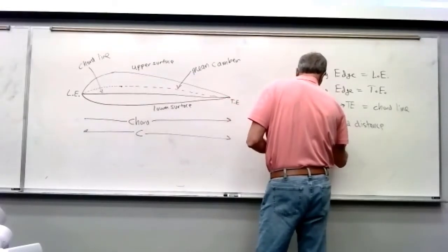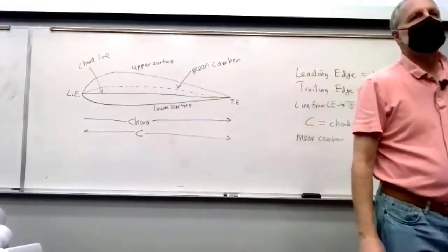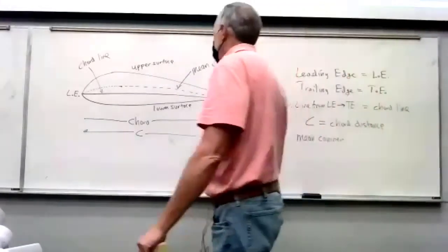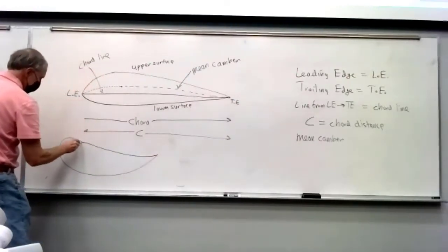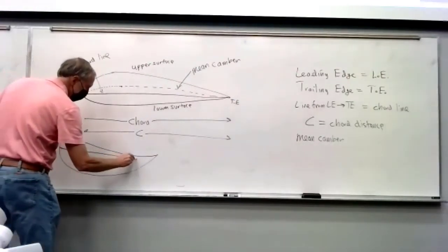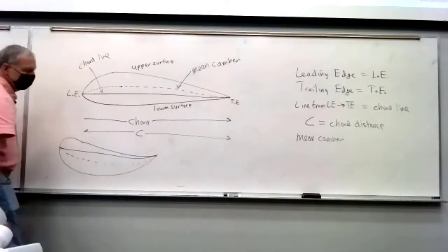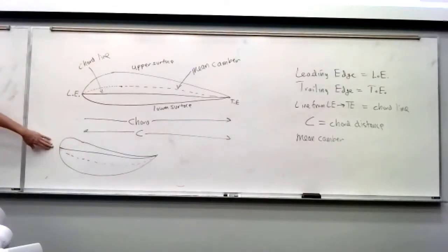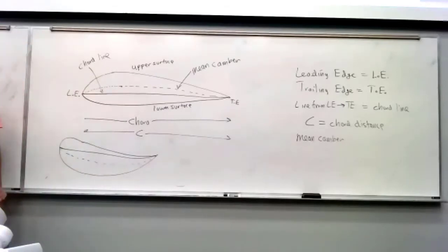Is that always on the upper surface? No, if you have an airfoil that's bigger on the bottom below the chord, then it could go that way. So it's just correlated to the bigger part? Yeah, because imagine an airfoil that looks like this. You have to draw from whatever first meets the flow, and then you can see you'd have a mean camber line that went like that. If we tilt it up to produce lift that way, it has a lot of drag. It's not a good airfoil design. So most airfoils that work well have a positive camber up above.